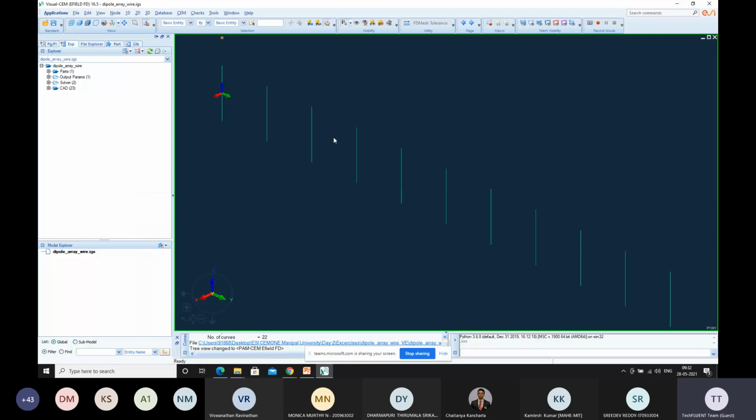The pattern will be greatly improved with respect to these particular elements we are using. Constructively, the radiation will be added up in both the side lobe and the other lobe. So two sides will be getting the added up gain. Initially, when we considered the half wavelength dipole, we got approximately 2.26 dB or 2.3 dB or so. Now we'll be getting a higher gain.